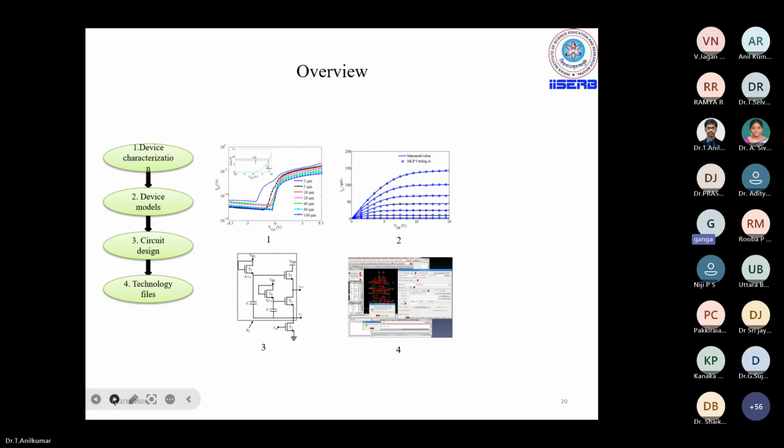First, we studied how the technology varies with respect to different channel lengths and so on. Then we developed device models. Actually, I did this work during my PhD, but of course now commercial device models are also available from foundries. And here the challenging aspect is we have to come up with novel circuit design techniques, because we can't adopt CMOS circuit designs here, because everything needs to be designed with N-type transistors.